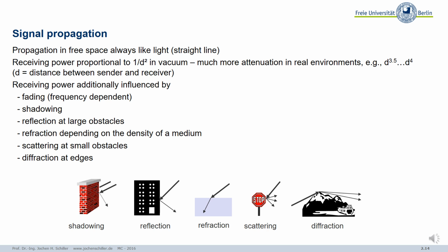You emit this, but the energy you receive here with your human body, if you are 100 meters away, 10 meters away, whatever, depends on the distance to the power of 3, 4, depending on obstacles, buildings, etc. So what you receive here is in the range of femtowatts, picowatts. Well, difficult to measure. You can measure it because you can receive it. But now compared to 1 watt, quarter watt, close by your brain with your mobile phone, these are factors of more than 1 million stronger, the energy, the signals, compared to the signals you receive from base stations.